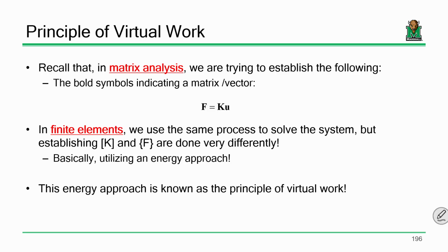That the force equals stiffness times displacement. And what we're after is defining these matrices, the force vector and the stiffness matrix. Once we have that, it's just matrix math to get the displacements. Now, up until now, we have been using what's called a direct stiffness approach. The direct stiffness approach being, here is a bar. Take that bar, yank on it. What is its response? That is a direct approach. Actually physically loading the bar and monitoring its response.